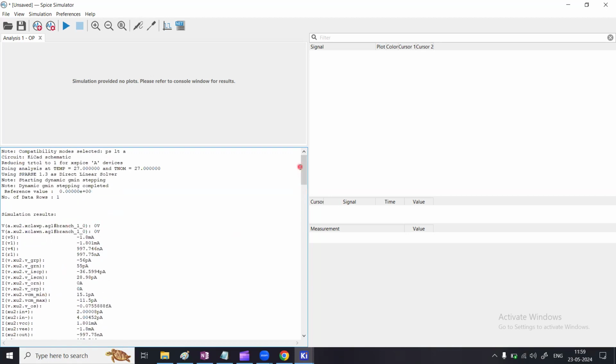We have successfully performed the DC operating point analysis, and then we also ran the FFT, but before FFT, we needed to carry out the transient analysis, and after transient analysis, we carried out FFT, where we saw the signal spectrum. And one more important analysis we did is the noise analysis. So hope you found this model useful.